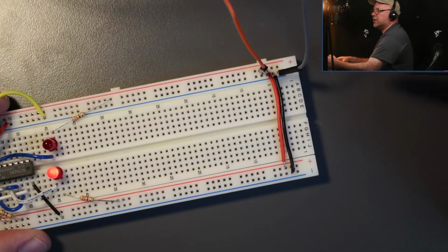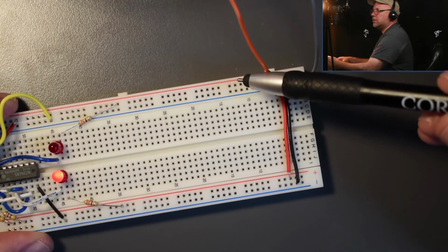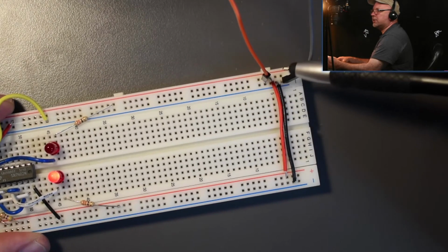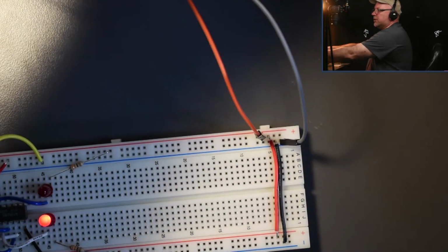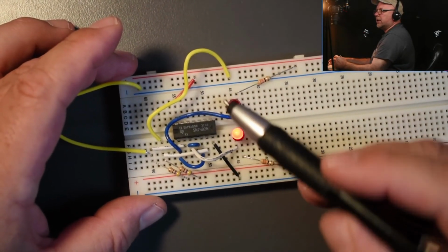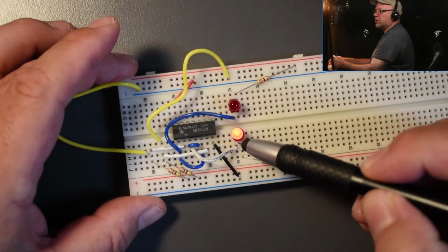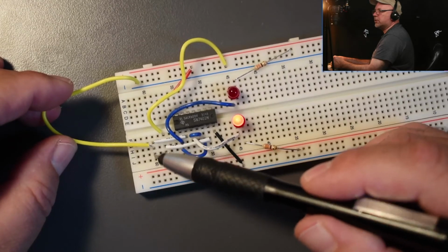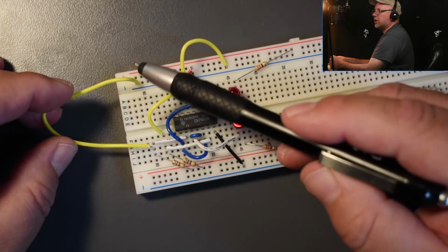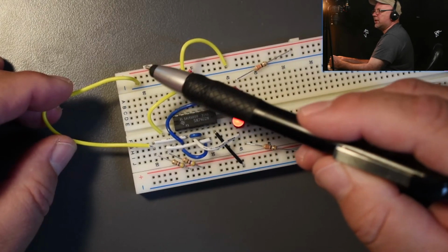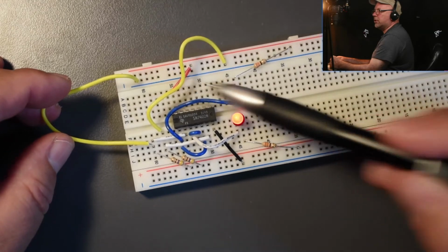So here we have the positive rail, red, and I brought it up to here, so we have the positive rails here and the negative rail here. This wire is set up to the power supply, to the 5 volts. Here is the Q, and the not Q is here. Instead of push button switches, which I didn't have, I'm going to simulate the switch with a wire. So here is the set, here is the reset. They are both brought to low.